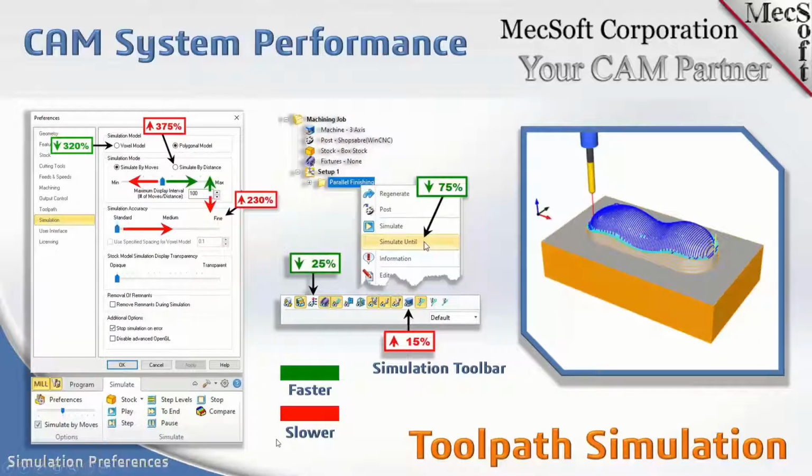Okay, so let's take a look at the default simulation preferences. On the left, you see the CAM preferences dialog. We're looking at the simulation tab. Now, these top 2 areas, simulation model and simulation mode. The mode correlates to, if you look at your simulate tab down below here, you have a checkbox for simulate by moves. So this correlates to the simulation mode. But let's talk about the simulation model.